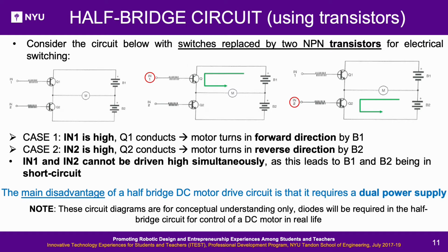The main disadvantage of a half-bridge DC motor drive circuit is that it requires a dual power supply. Note: these circuit diagrams are for conceptual understanding only. Diodes will be required in the half-bridge circuit for control of a DC motor in real life.